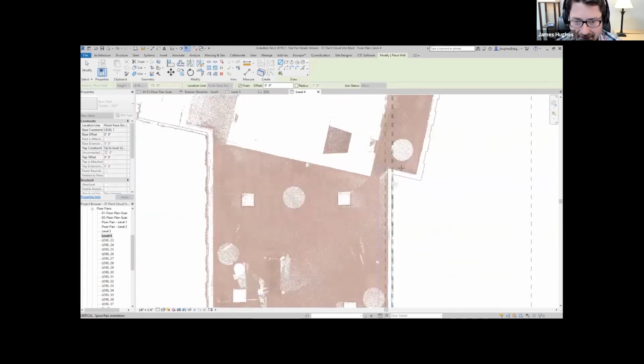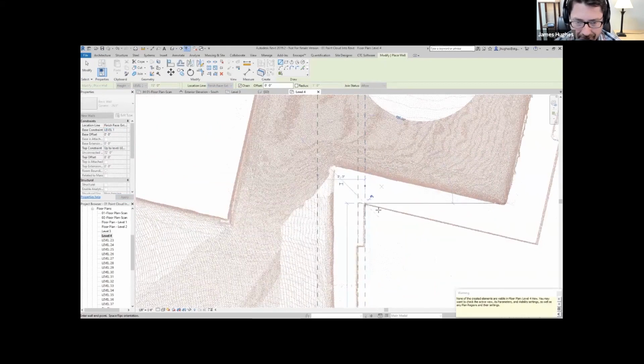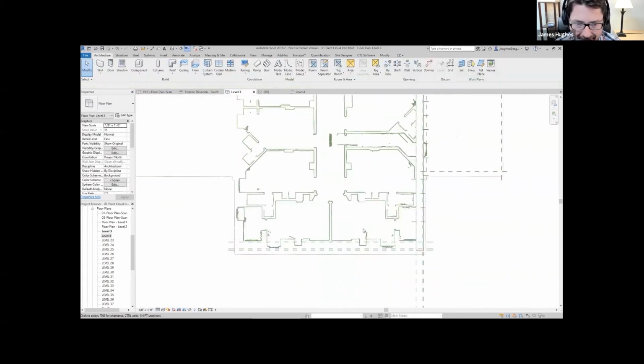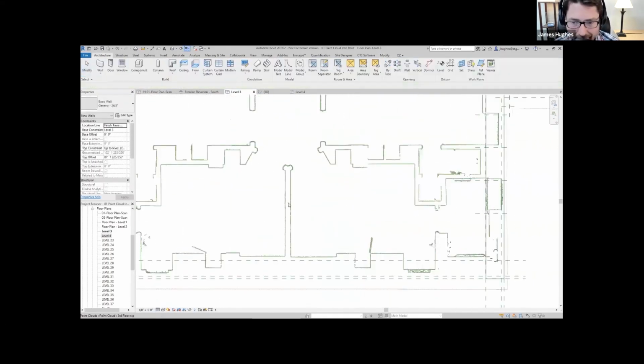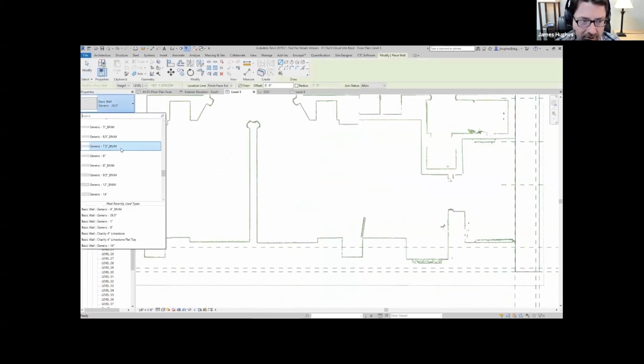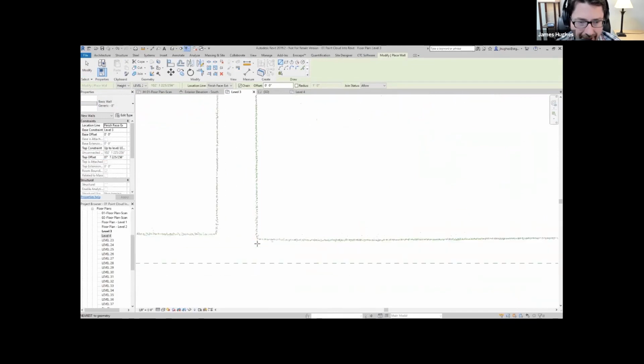And we're going to pass this main wall way, way north. It's invisible. I need to turn that on. There we go. And up it to fine level detail. Hit the space bar to flip it. And interior walls go easier. That measures 8 inches, so we'll just select a generic 8-inch wall for now.